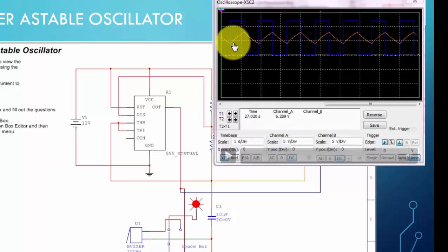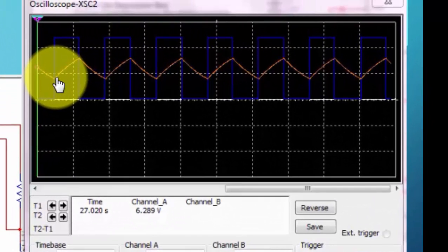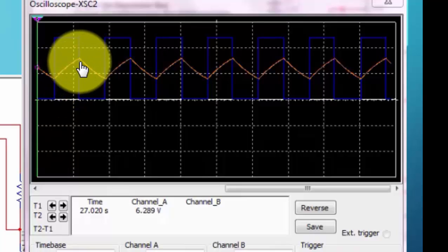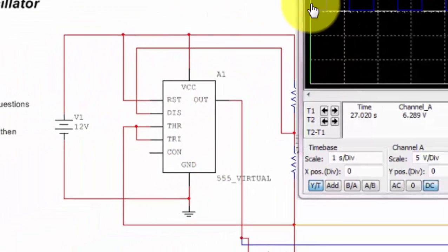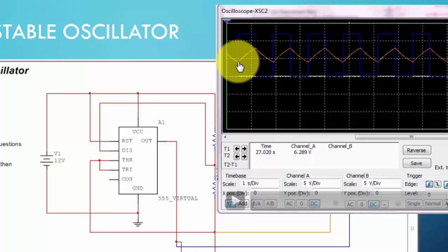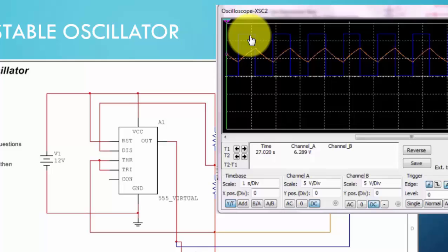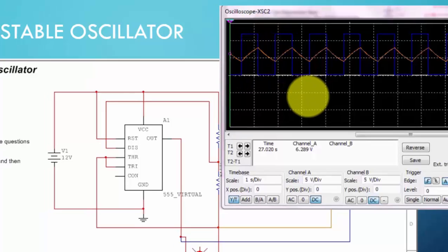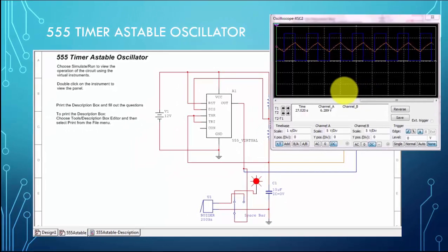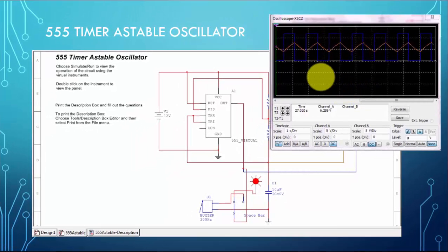The threshold values are used to determine the frequency and timing of this device. So we have threshold points for the capacitor here, and inside the circuitry they sense these voltage levels so that they can provide the proper amount of period to give a certain frequency. In the next slide I'll show you the formula in terms of R1, R2, and C1.